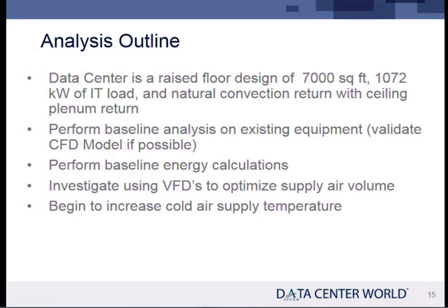The other thing that TC 90.4 does is it gives a requirement to set the specification of energy efficiency at full load, which everybody designs for. I work with a lot of design build firms, and they're all working at max load. In other words, when I design a data center, I have to make sure it'll handle peak load. Great. Day one, I don't have peak load. Day one, I've got 10%, 20%. How efficient is it at 10% and 20%? No one's ever done the math. Answer is, it's not very efficient at all, right? Because the energy required to drive that chiller is still quite high compared to the IT load.